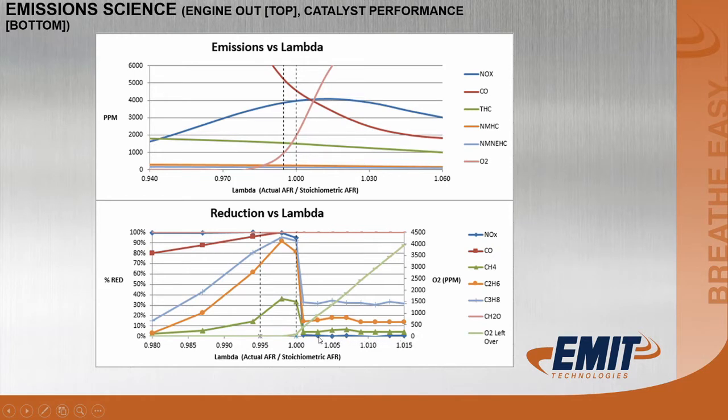Our NOx has literally been taken down to nothing. Our CO is below this line, hanging down here right with the NOx. And you can see some of our other unburned hydrocarbons don't reduce quite as well, but they're certainly reducing by quite a bit. We're at least getting the 40% reduction.